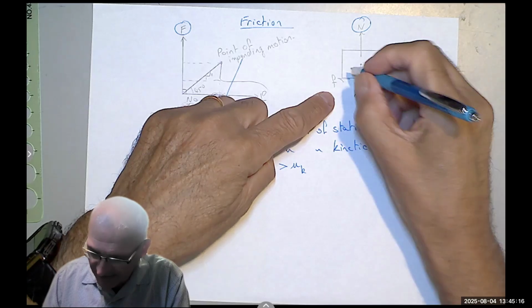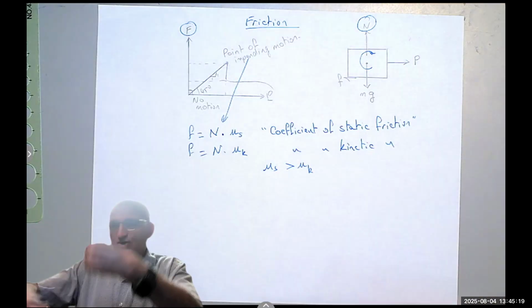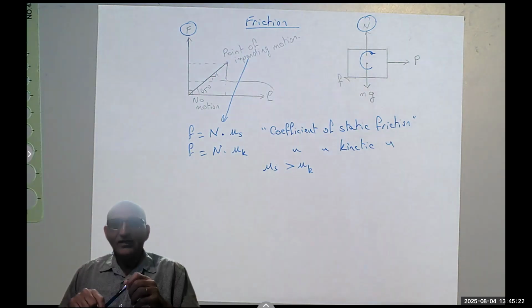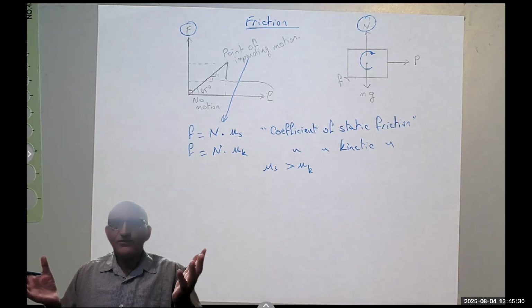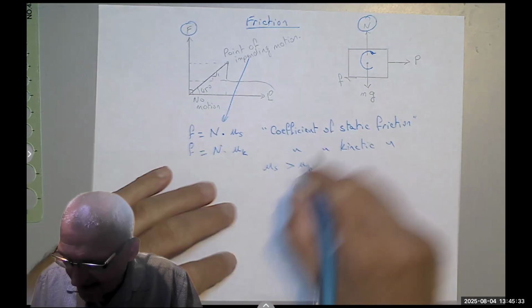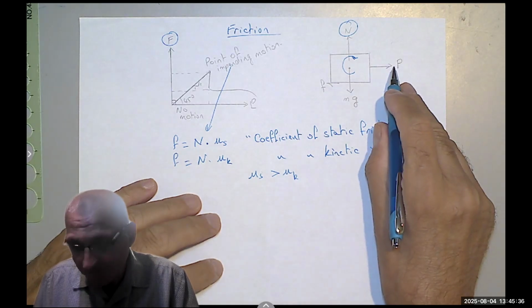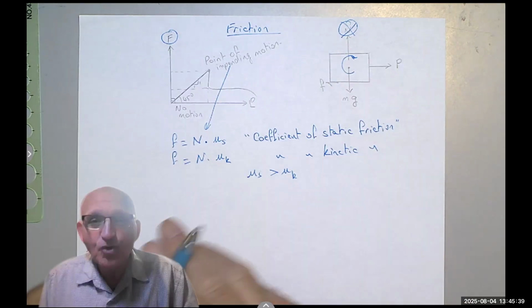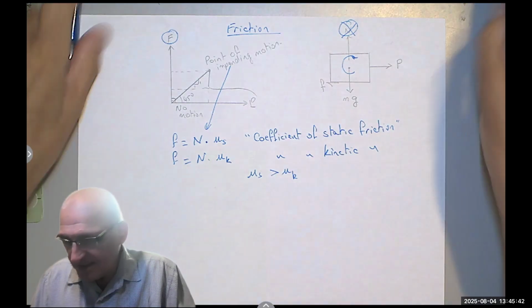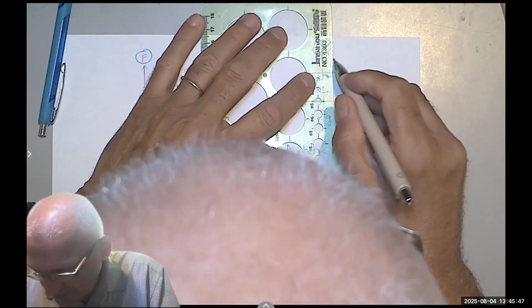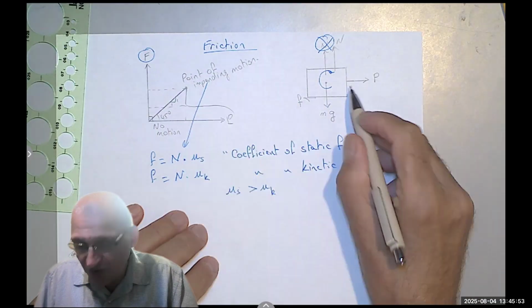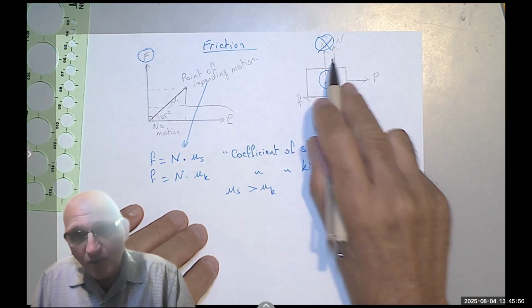If you draw this couple like that, then definitely this thing is rotating. It keeps moving. There's no way. What keeps it from tipping? The only explanation is that once you apply a force, N is no longer collinear with mg. It slides to the right. It's as if the P is pulling N with it. It goes here. If you didn't reach this point, so you have to pull more, N will go more.